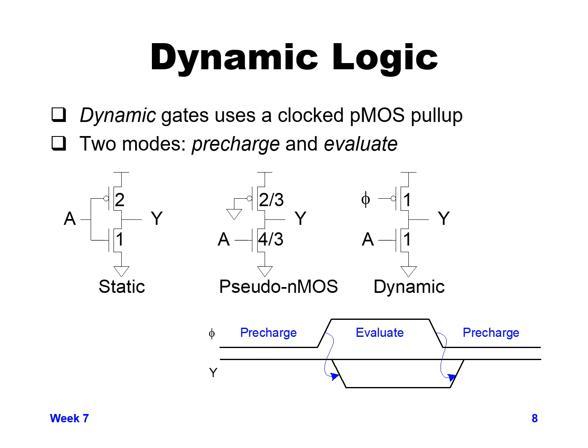And so we have a clock, phi, coming in, and when it's low, we're pre-charging the output value. So we're charging Y up. Before we plan on evaluating it, we make sure to charge our output to 1.